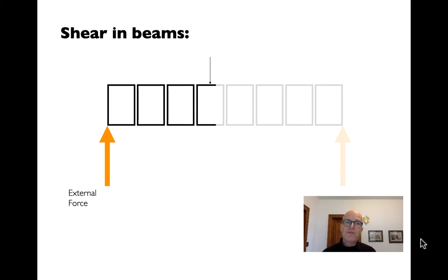When we move along the beam, when we get past that first load, now think about how we can keep this free body in position. We have an external force pushing up, we have an external load pushing down. We're going to have an internal stress that has to be the differential between the reaction on the left and the load that we're applying somewhere in the middle.